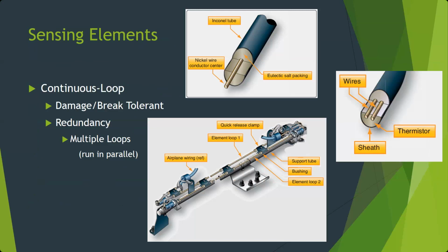Okay. The other one is these will be around the engine. When you close the cowl, you won't realize that it's touching the metal on the inside of the cowling, because you're always looking at it with the cowl open, trying to figure out why it keeps giving a false signal. And then you close it and there's metal somewhere touching. So you look very carefully along the length of it for chafing or signs where it's touched the metal. And they're bendable. You kind of just bend them out of the way. Most of the time, that's all you got to do. Or replace the little grommet if it went missing.